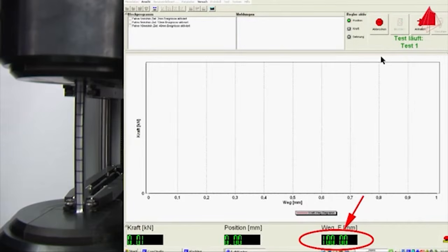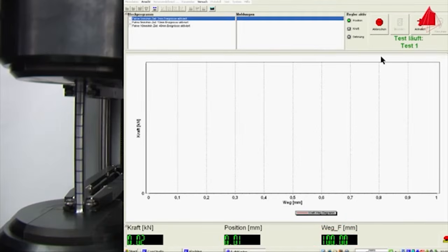And now we have a graph. The gauge length, or the initial length of the specimen, is what is shown there, so the value set there is 100 mm. That is what our extensometer reads. And take note that our specimen is constantly elongated, with a constant speed of stretching by our machine. So now our experiment has started and you can see that our values have risen. Now our specimen is resisting the tensile force of our machine, and its force is shown on the screen.